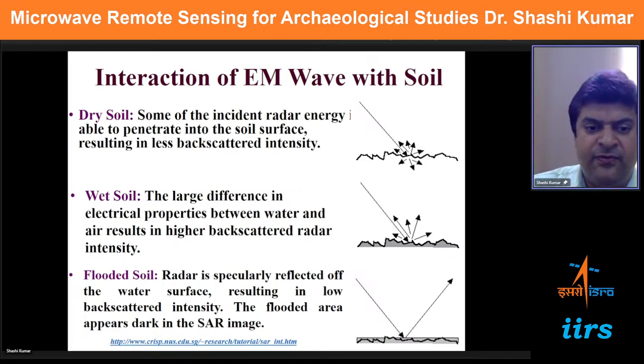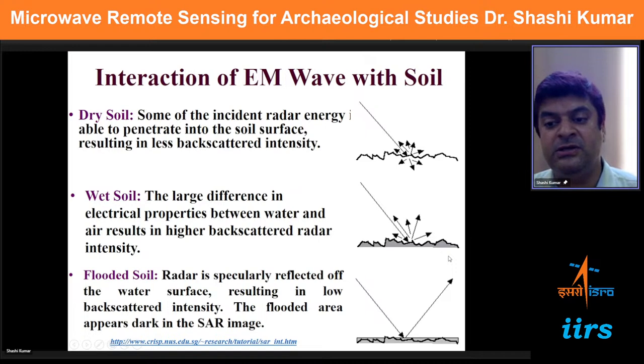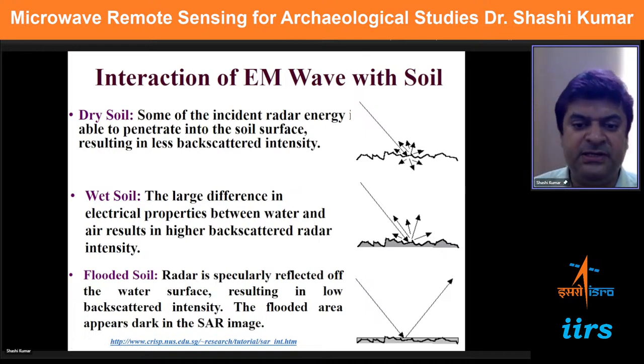And in the case of flood, we cannot get any penetration, because the entire surface will be covered by the water body, and whatever amount is transmitted by the sensor, the entire amount will be reflected away from the direction of the sensor, because SAR waves cannot penetrate the water body. When water comes into the picture, microwaves or SAR waves are going to surrender.